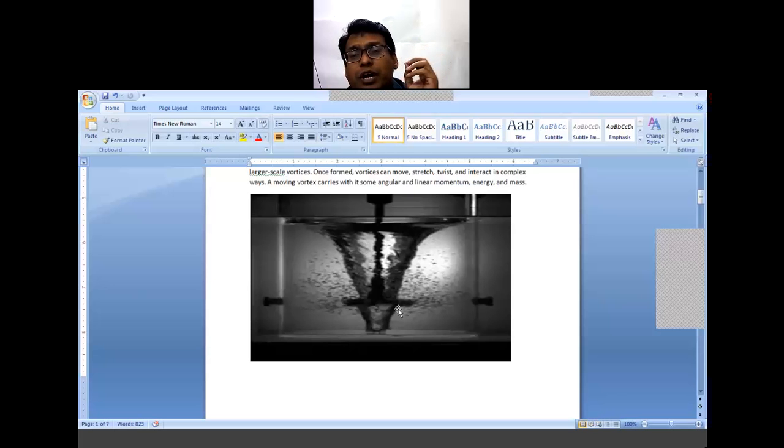That damage to your impeller quality is to be avoided by providing baffles, because providing baffles is very simple, and it helps to reduce the vortex formation and prevent damage to the impellers.